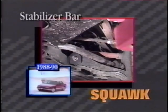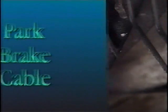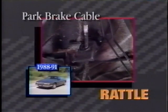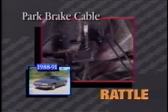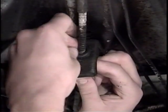A squawk noise coming from the front on some cars may be produced by the front insulators. The park brake cable may also cause noise. For example, a loose cable that contacts the underbody as the car is driven may produce a dull rattle noise. Ensure that the cable support brackets are not damaged and the cable grommets are properly installed in the brackets and the cable is lubricated.